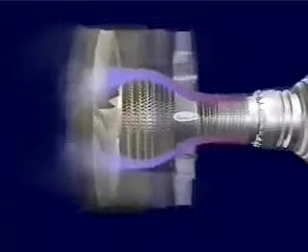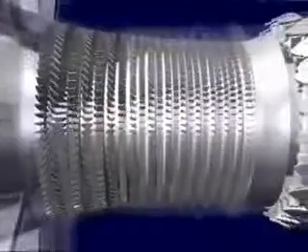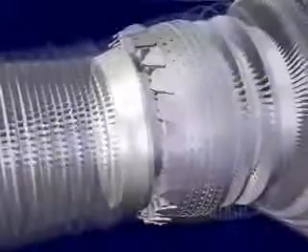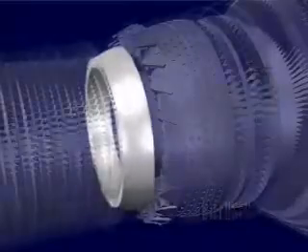After the air has passed through both compressors, it is 35 times higher in pressure and 1,000 degrees hotter than the outside air. The compressed air is now at the right pressure, but it is moving too fast to be efficiently ignited, so it enters a diffuser, where it slows down while remaining at the optimum temperature and pressure.